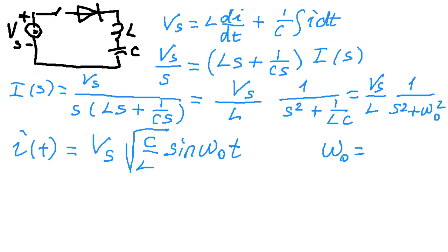So this is a resonant network. It's an ideal network. Of course, every inductance has a resistance, and every capacitor has a resistor because of their inherent structure. But if you neglect those resistors, that equation is valid. Omega o is equal to 1 over square root of LC. It's a well-known resonant network. So a DC network actually produces AC.